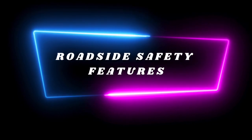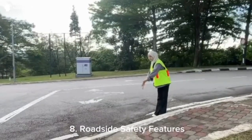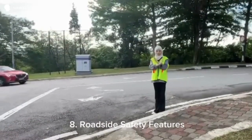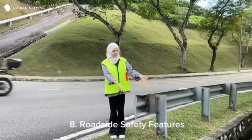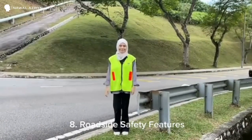Roadside safety features. We observe that the paint markings on the road such as lane lines and signage are fading or nearly disappearing. This can confuse drivers, especially at night or during bad weather, and it may lead to accidents due to unclear road guidance. Next, we also observe that some of the road barriers or guardrails are not in good condition, especially at the sharp corners.